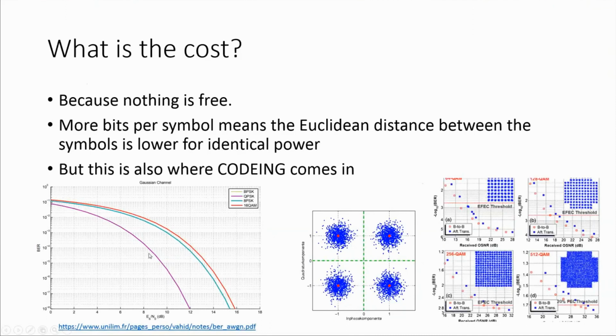And you'll see that in this bit error rate curve. For a Gaussian channel, which is just a flat noise that we talked about, which is why we talked about it, because you'll see this, and I wanted you to know what it meant. Here's our energy per bit to noise in 1 Hertz ratio, proportional to SNR, and here's our bit error rate, which is the number of errors per bit transmitted. BPSK and QPSK are exactly the same, because BPSK is just 2 of these.